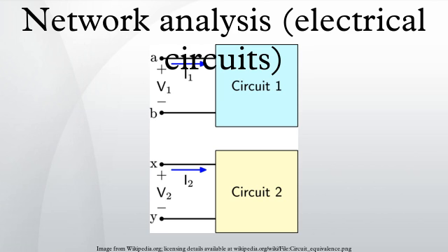Note that mesh analysis and nodal analysis also implicitly use superposition, so these two are only applicable to linear circuits. Superposition cannot be used to find total power consumed by elements even in linear circuits. Power varies according to the square of total voltage or current, and the square of the sum is not generally equal to the sum of the squares.